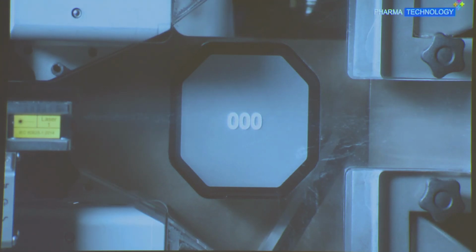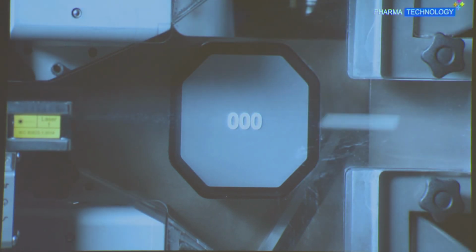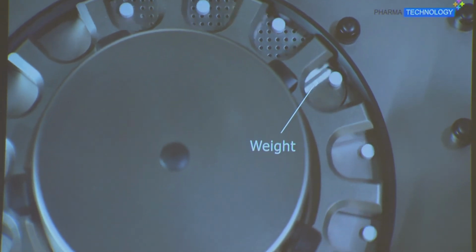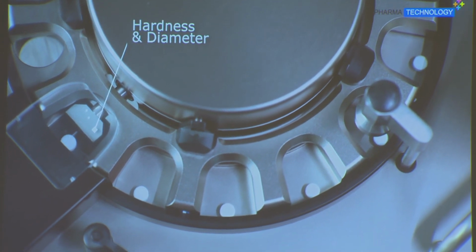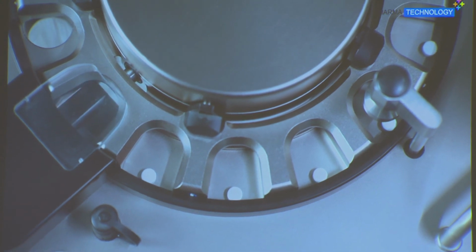Directly after the mass measurement, out-of-specification tablets are removed, while correct ones are transferred into the conform product bin by the fast reject gate. In addition, a rejection confirmation sensor guarantees that non-conform products are correctly discarded. At regular intervals, samples are diverted to the high-precision weight cell to continuously maintain the calibration of the 3D microwave resonator. The 4-parameter tester can be added as an option to measure the weight, thickness, length, diameter and hardness.